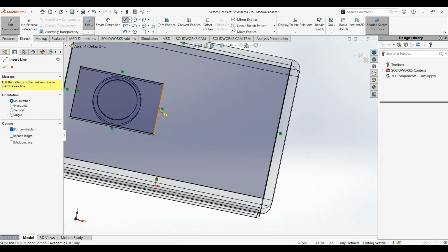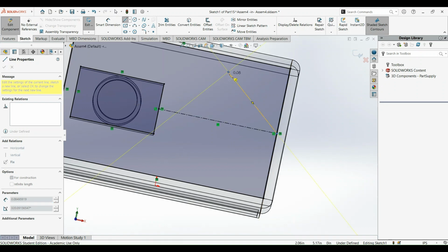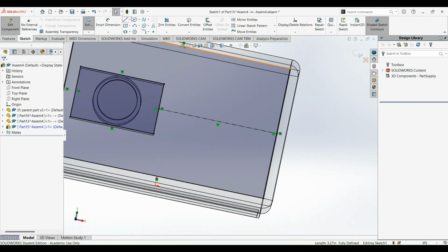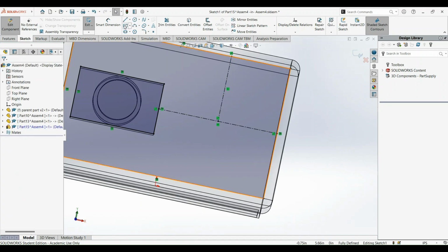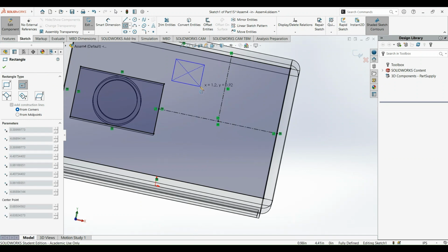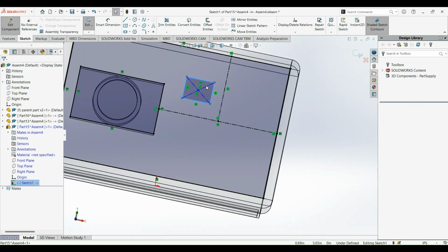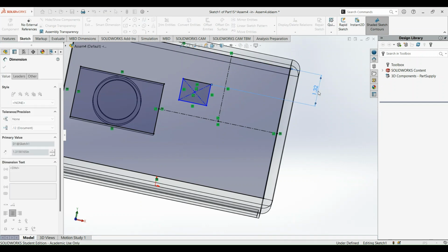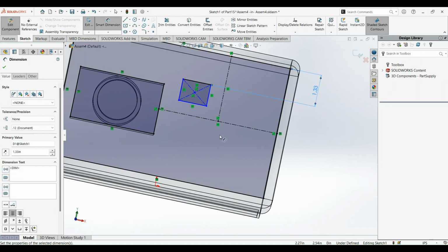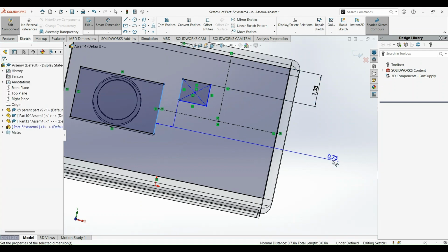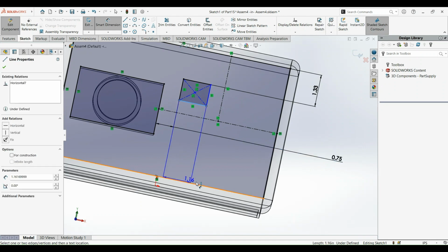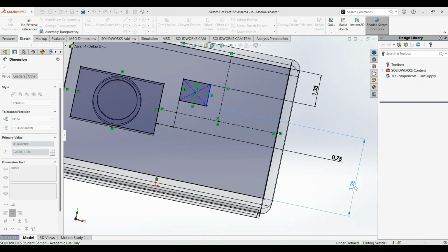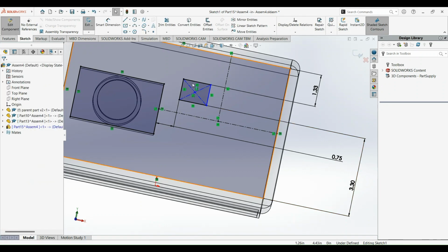Okay, now I'm going to create buttons on the front of the projector. So again, I do insert new part, and then I select the front surface of the projector, and then I use the convert identities feature, and then I use the rectangle tool and reference geometry lines to create a single button part, and then I mirror that button part across the horizontal and the vertical axis, giving me 4 buttons, and then I use the extrude to create the thickness of the buttons.